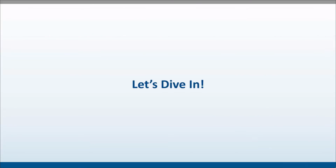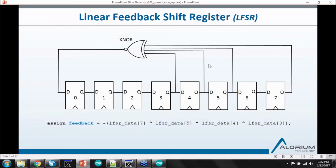All right. So the linear feedback shift register that we're creating today is this 4-tap LFSR, and we've chosen this polynomial pretty arbitrarily, but we're tapping out at bits 7, 5, 4, and 3. You would be able to change this in the design if you wanted to and see the effect of that. But just for reference, this is what we'll be seeing today.